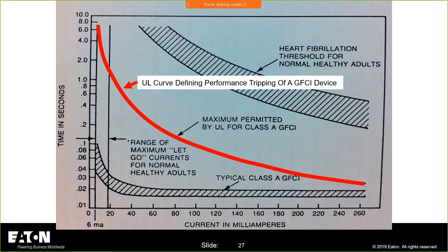And the answer is no, you're not assured of that. It's going to prevent that abrupt stop at the bottom, but you don't know what might happen to you. Even though you're wearing your fall protection, even though you have that GFCI, there may be other circumstances that could still lead to shock. You'll reduce the incidence significantly, but it doesn't mean it's a sure thing.